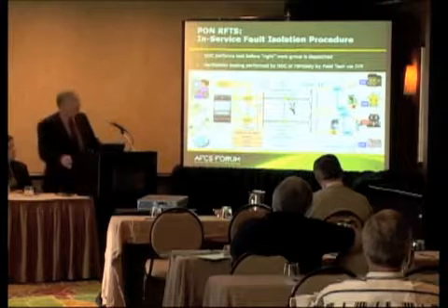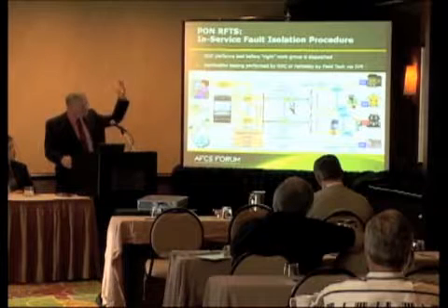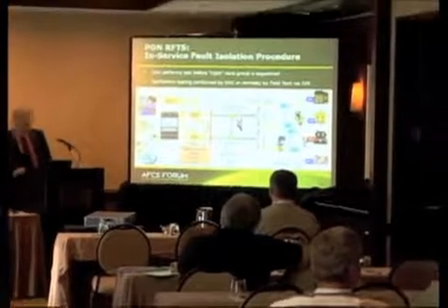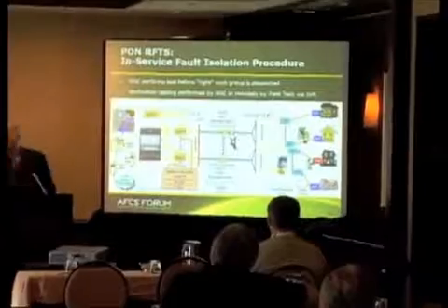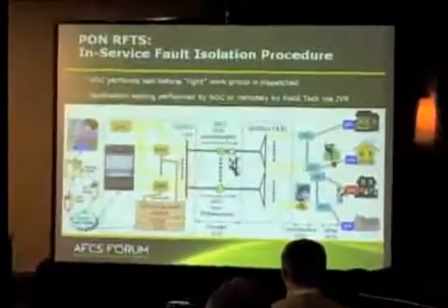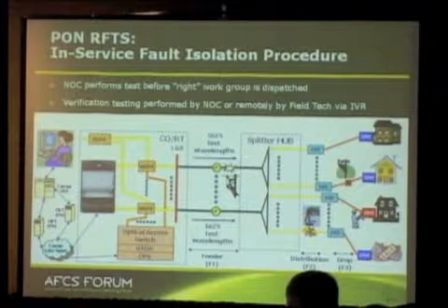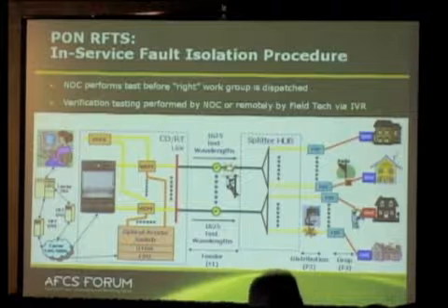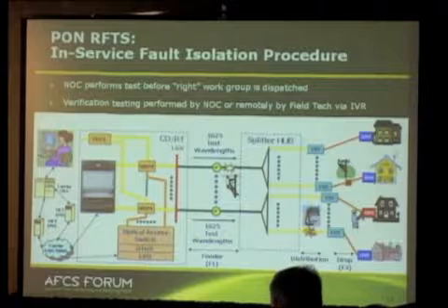We could have an issue if you have a large central office and you have intra-building cabling. We've found a lot of people having problems with that at their patch panels and stuff. So we can detect anything beyond where our access point is. If it's from an access point back, we can't tell. But even that says, if we got 32 customers out and we're good to go all the way out, then the presumption is the problem is in the CO.